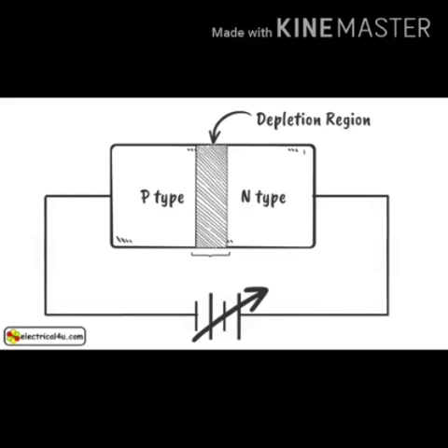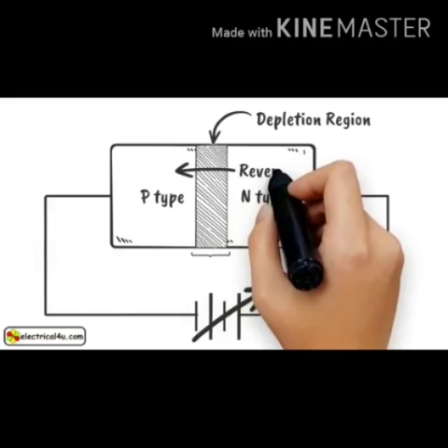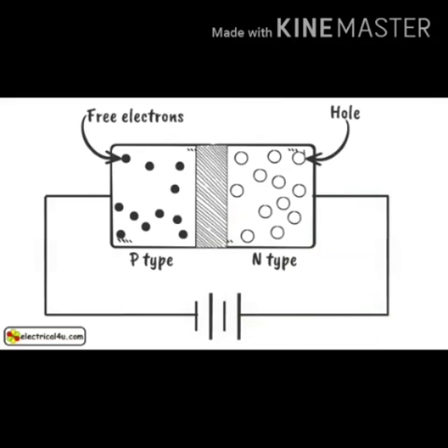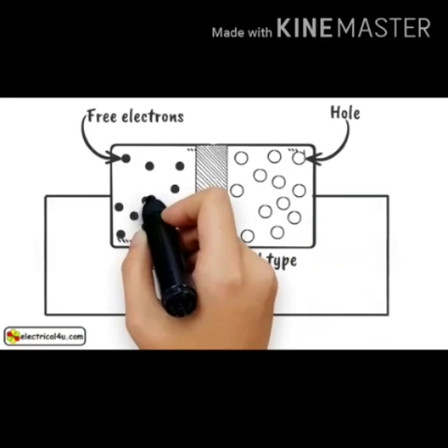The newly generated charge carriers are also accelerated by the electric field, resulting in more collisions and further production of charge carriers. The cumulative process leads to an avalanche of charge carriers across the junction and consequently reduces the reverse resistance.